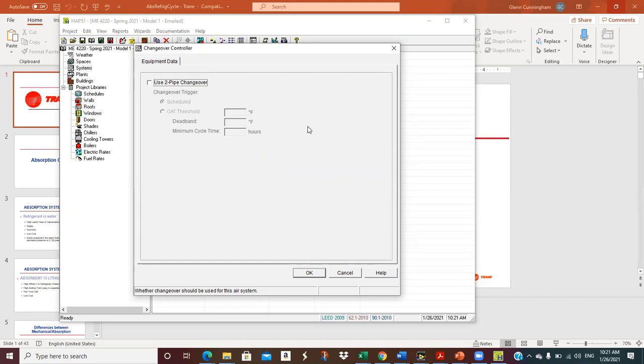Well, in September, October, November, we get days that may be 40, 35, but they might turn around and get up to 75. So we'd really like to have hot water at night and chill water from 9 o'clock in the morning until 5 o'clock or something like that. So that's what they mean by changeover.